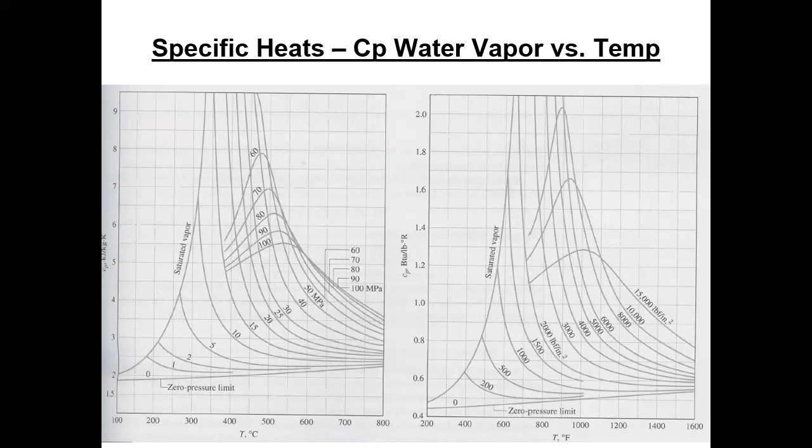The old number that I always remember for water, in US units, the specific heat, CP, which would give you an enthalpy number, is 1. That says that one BTU is the amount of energy it takes to change 1 pound of water 1 degree Rankine, but the size of a degree Rankine is the same as a degree Fahrenheit. It's just the scale that changed.